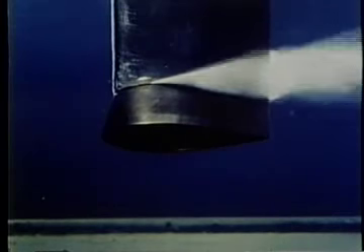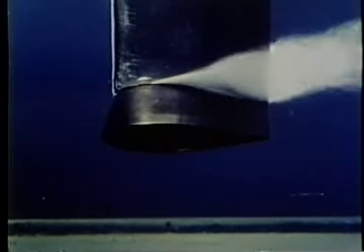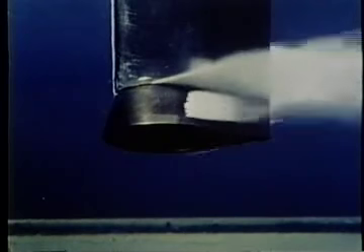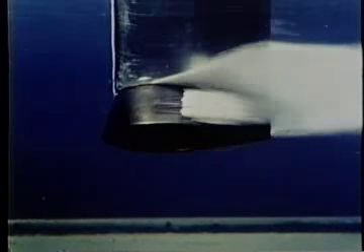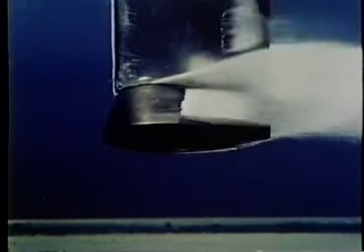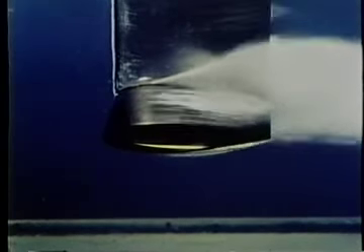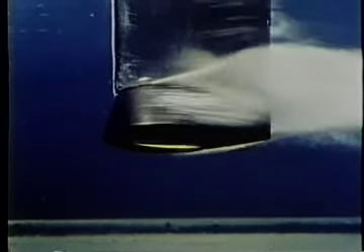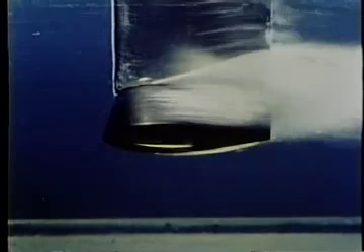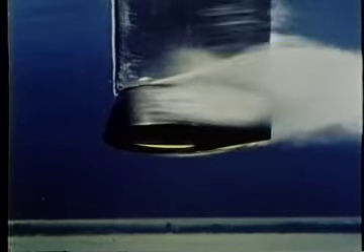At low speed, cavitation on the foil itself first occurs in the low-pressure core of the laminar boundary layer separation region associated with low Reynolds number. At higher speed, and thus larger Reynolds number, the appearance of the cavitational flow changes. Transition from laminar to turbulent boundary layer has occurred. Laminar separation has been suppressed, and cavitation now begins near the minimum pressure point close to the leading edge.